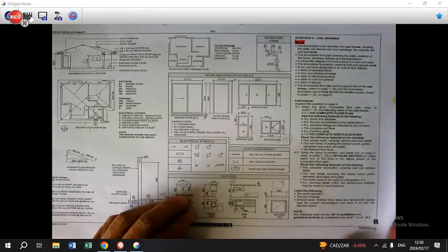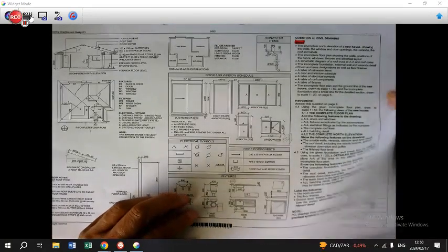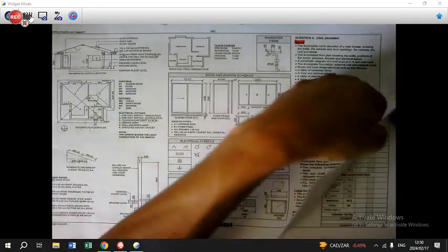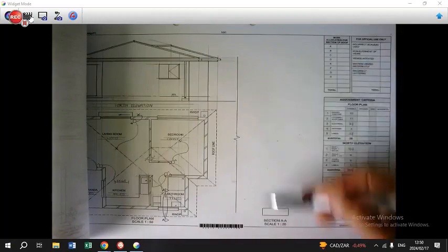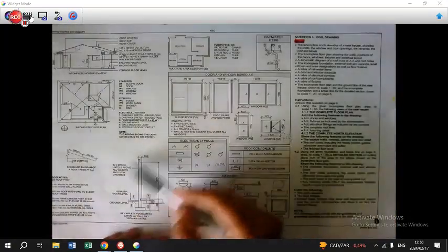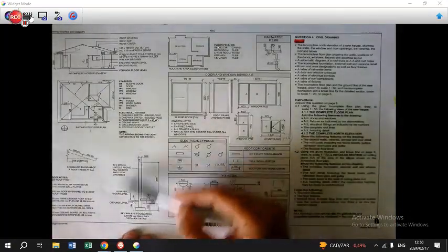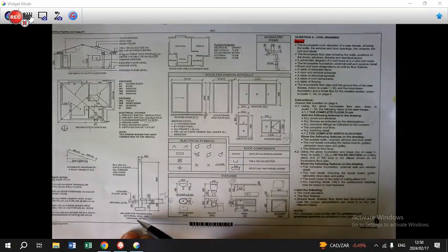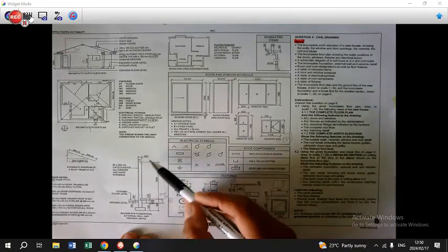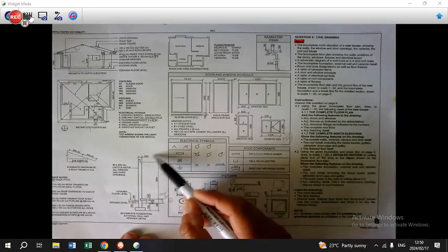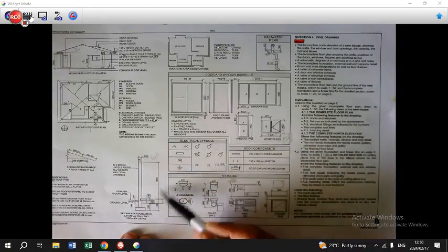Our approach to this drawing, learners, will have 3 phases, of which you are going to have phase 1, which is going to be your substructure, and we will start with this component here, which is your incomplete foundation, external wall and veranda detail, where you are going to divide all the different dimensions here to a scale of 1:20, which means that everything here will be divided by 20.